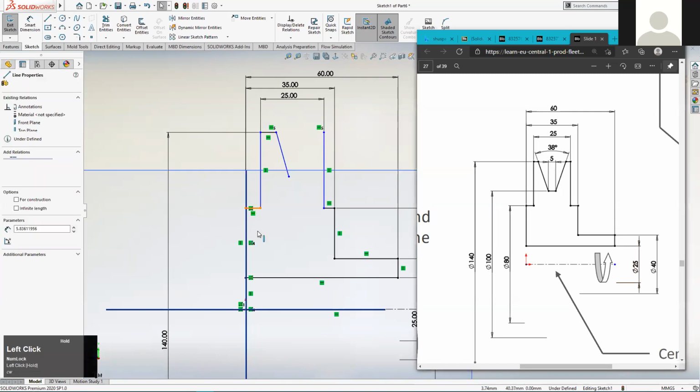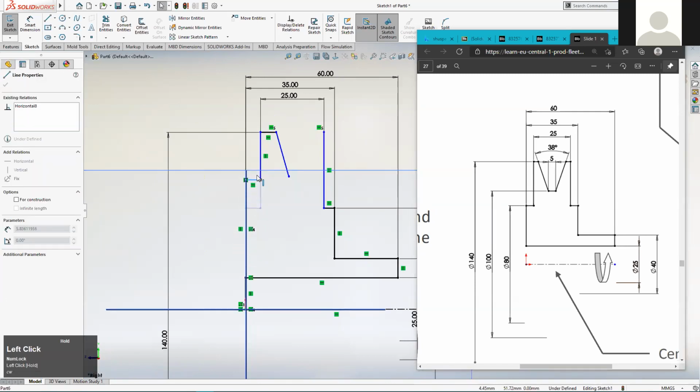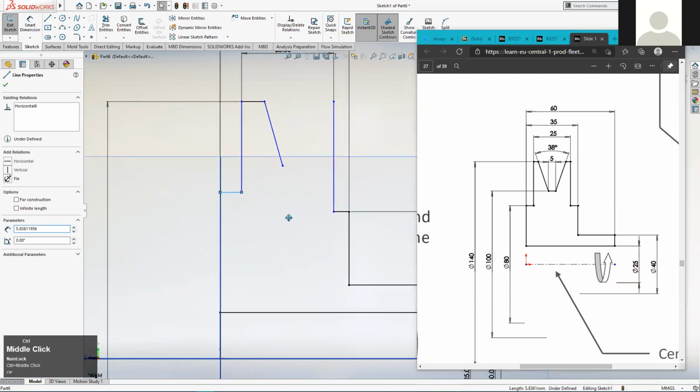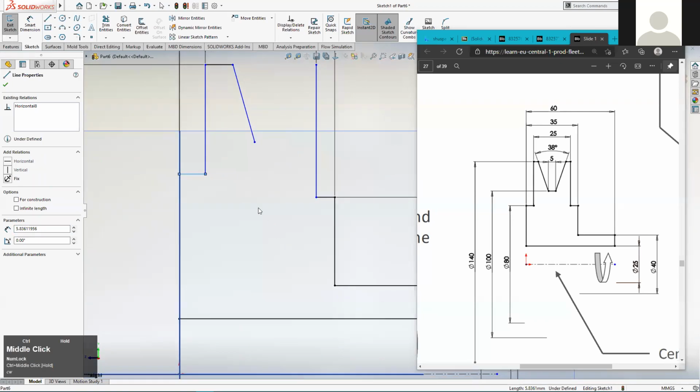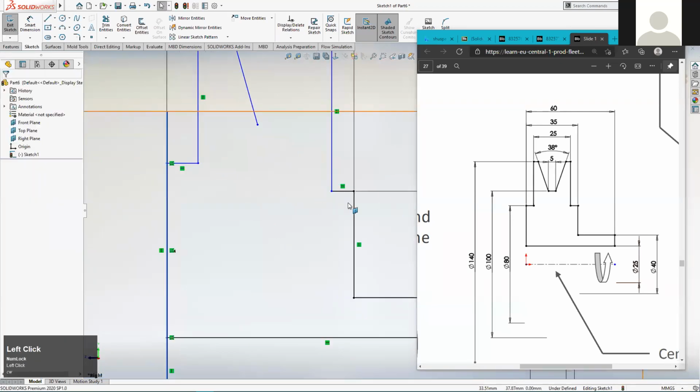Are these two aligned? Again, you can drag these sketches around to try and figure out how they're underdefined still. So you can see I'm dragging that edge up and down. That edge should be aligned with that edge there. So we'll use a slightly different type of relation because we're kind of learning what all the different relations mean. So what I'll do is I'll click on the entirety of one of these edges rather than a point on the end. So like that. Make sure you don't click on the dead center because that will pick the center point of the edge like we used in that other example. So click sort of in one of the quarters of the edge.